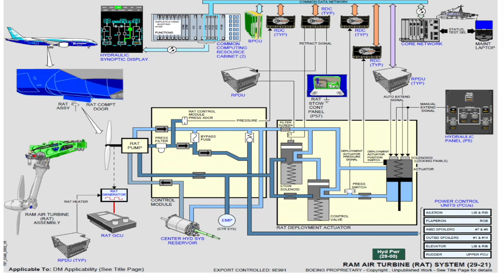Engine-driven hydraulic output would begin collapsing once both engines were no longer producing power. The center hydraulic is not engine-driven, however. It is driven by an electric motor pump. If the three hydraulic systems decayed very rapidly, this could trigger RAT deployment on a short timescale. No documented automatic deployment pathway other than the immediate condition triggers is consistent with the observed 3 to 5 second deployment window.